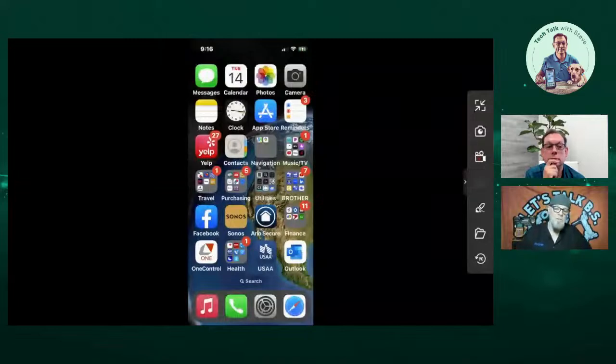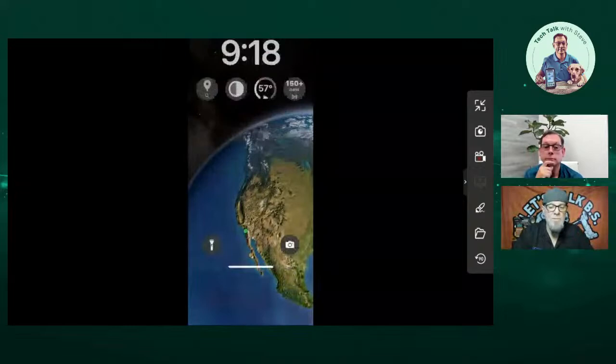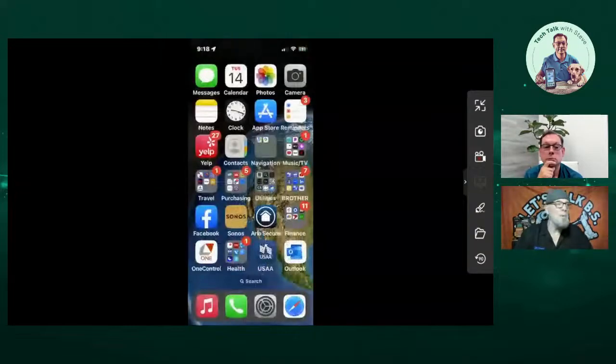So I'm a tech in San Diego, and I've got a whole bunch of labeling to do based upon the certifying that has already been pre-done. Now, in accordance with EIA/TIA 606-D, there's a couple of things I need to label. Two of the most crucial things I need to label are, number one, my patch panels, all right? Number two is the associated label, which is the same identifier on the backside, which is going to be the cable. And hopefully nothing pops up on here. I think I got rid of all my pop-ups, but if something does, I'll try and get rid of it as soon as I possibly can.